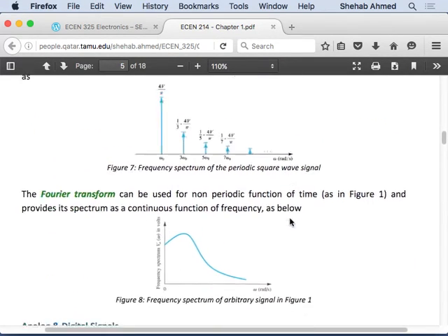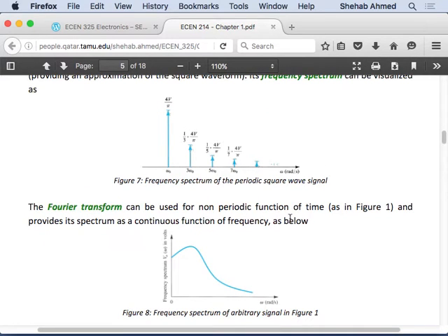We talked about this. So again, the difference between the output of Fourier series and the output of Fourier transform is the fact that Fourier series is applied to periodic signals. So something that keeps repeating. Right? It's non-sinusoidal, but keeps repeating. If you have a waveform that is just a wiggly waveform, so it's non-sinusoidal, but it's non-periodic, then you have to apply Fourier transform. With Fourier transform, you don't get discrete frequency components like we got for Fourier series. Right? That's the difference between Fourier series and Fourier transform.